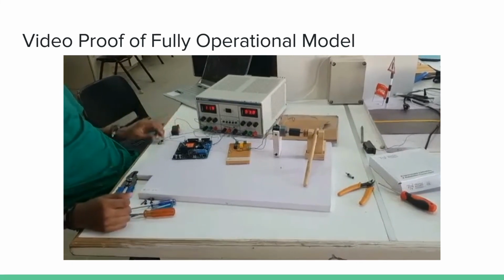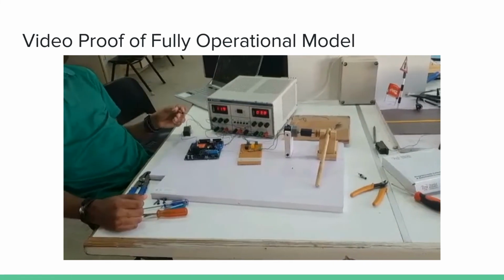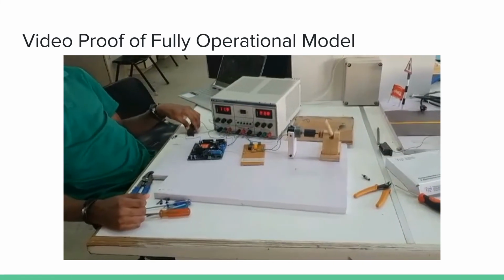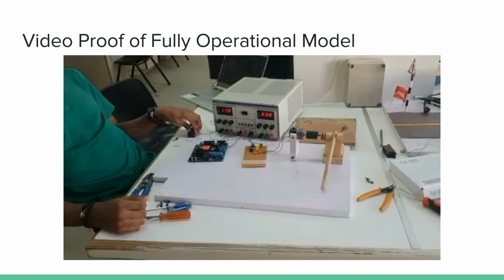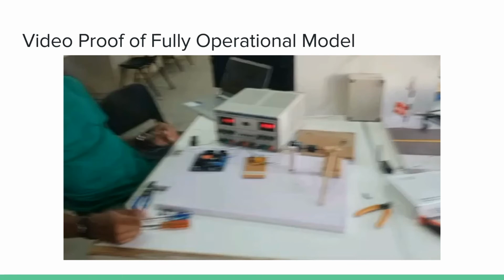When the car park is at max capacity, cars need to exit on the other end, passing the other sensor, allowing other cars to enter. The count of spaces is controlled by a counter. The entrance sensor registers a negative count from 6 down to 0, and the exit sensor registers a positive count, adding 1 free space every time a car exits from that side.